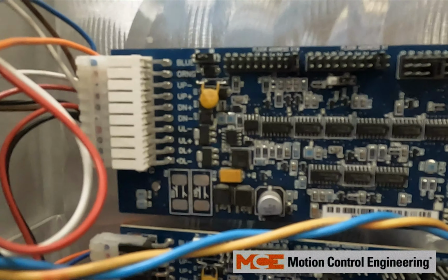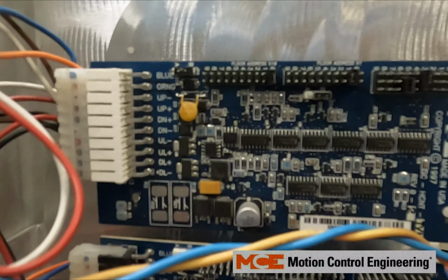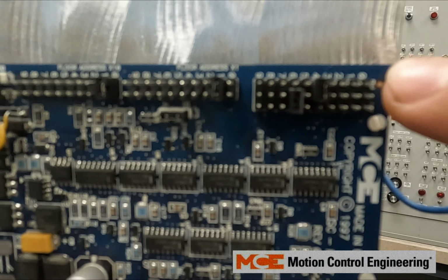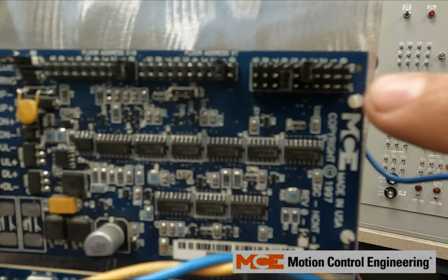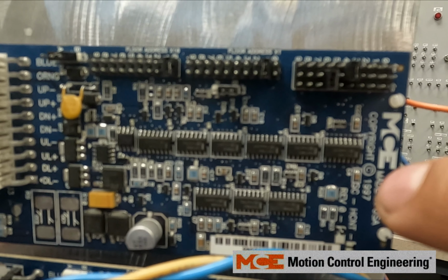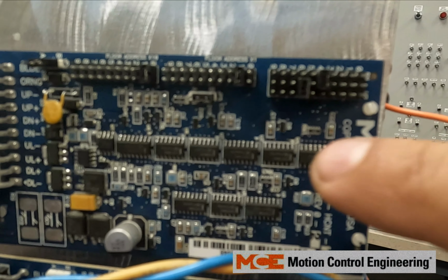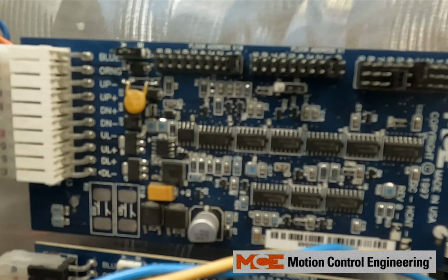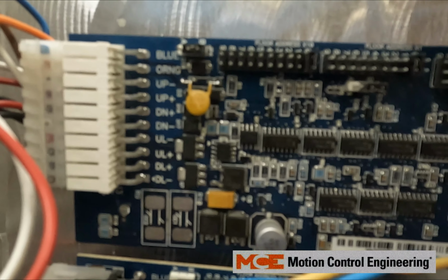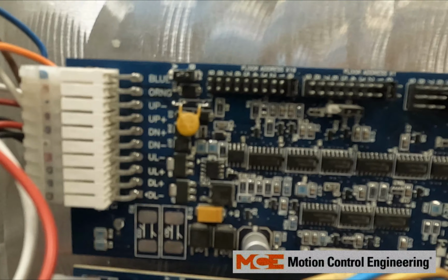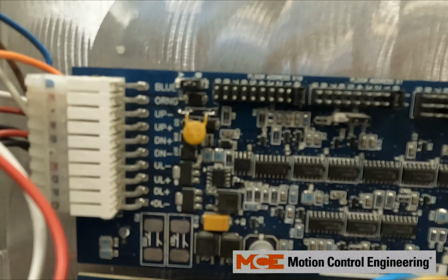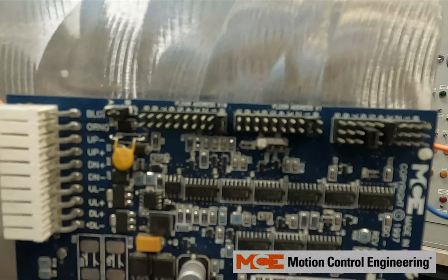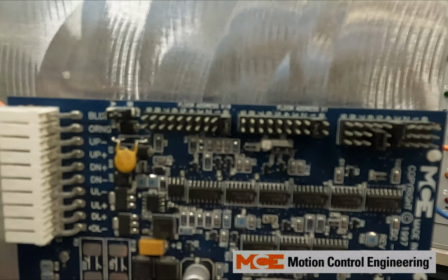As you notice here, this is just the front main up and down. Right here you have the down and the up, and we have jumpers for 4 down, and then for up we have jumper 6. For floor address, floor 1, you have the 0 for X10, and then you have a 1 for X1.